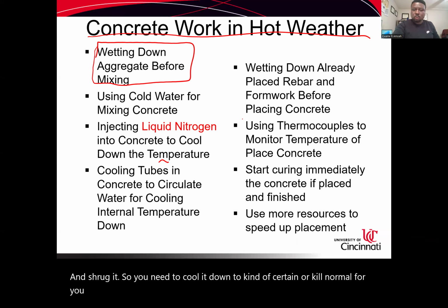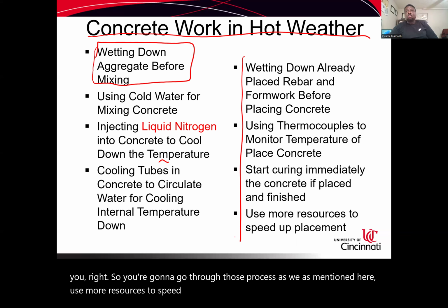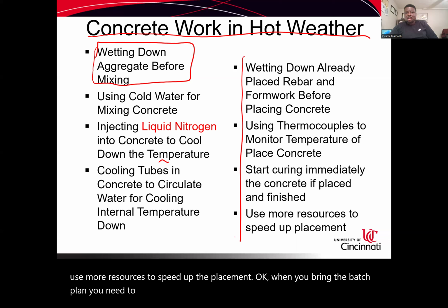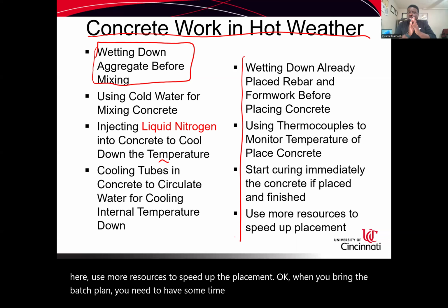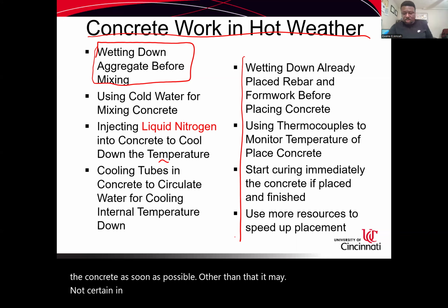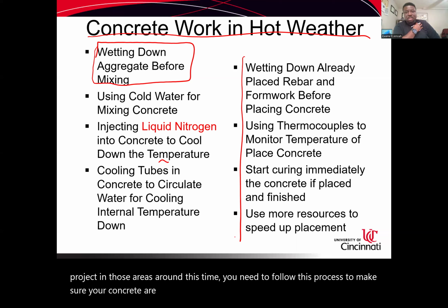So you're going to go through those processes as mentioned here. Use more resources to speed up the placement. Okay, when you bring the batch plant, you need to place the concrete within a short period of time, as soon as possible. Other than that, it may harden or settle in those drums, right? So very important. If you're supervising a project in those areas around this time, you need to follow this process to make sure your concrete is cool and gets the required quality mix that it desires.